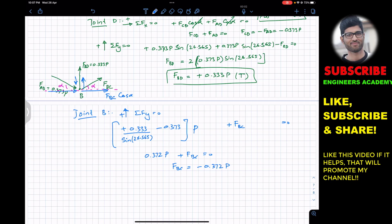And the negative sign tells us that FBC is acting towards this joint B. So this means that the BC member is in compression. So FBC is 0.372P, and this is also in compression.